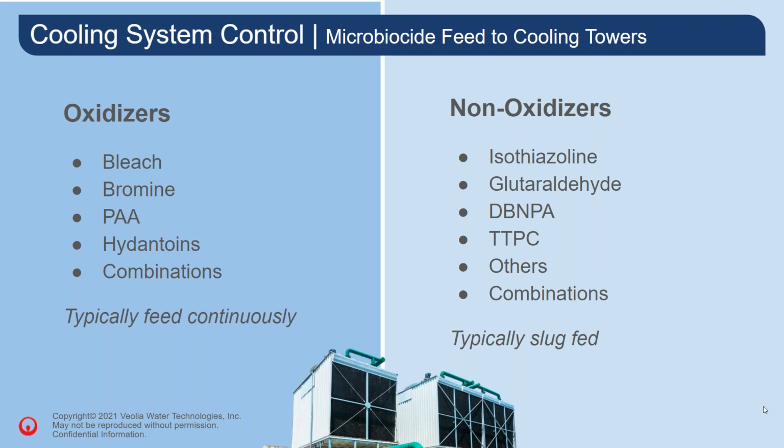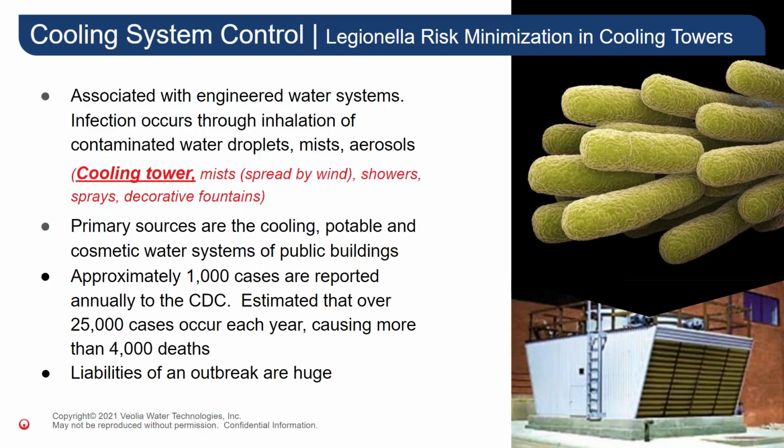And one thing to note, since microbes are present in every water, their presence alone is not a cause for fear. Their uncontrolled growth is the problem in our cooling system, so we seek to control microorganisms. Sterilizing a cooling system open to the atmosphere and operating as a large air washer just isn't practical, nor is it necessary.